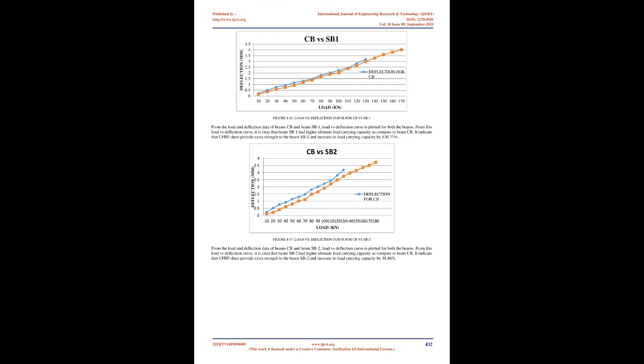Load deflection history. Load deflection history of all the beams was recorded. The midspan deflection of the control and strengthened beams was measured at different load steps, and the deflections under the point loads were also recorded. The load deflection histories are illustrated in figures 4.11 to 4.20. These figures show that the deflection curve was initially straight, showing the linear relationship between the load and deflection, and became nonlinear with further increase in load.